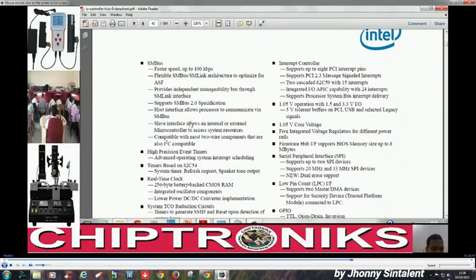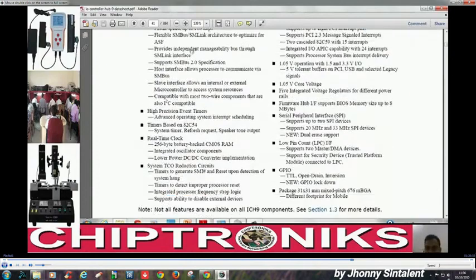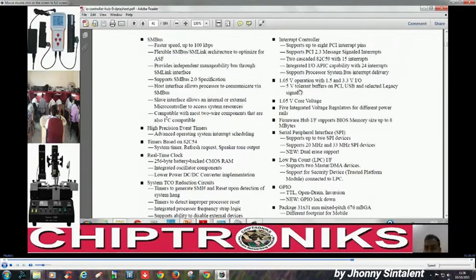and in the next page we can see the SM bus controller. We'll discuss this also. And real-time clock, you see the real-time clock is there. We have already tested how to test this RTC section. Now a very important description is 1.05 volt operation with 1.5 and 3.3 volt I/O. Please mark this statement, because we are going to use this line afterwards. Mark it, this is very important. And 1.05 volt core voltage, this is the core voltage for the ICH, not the processor.